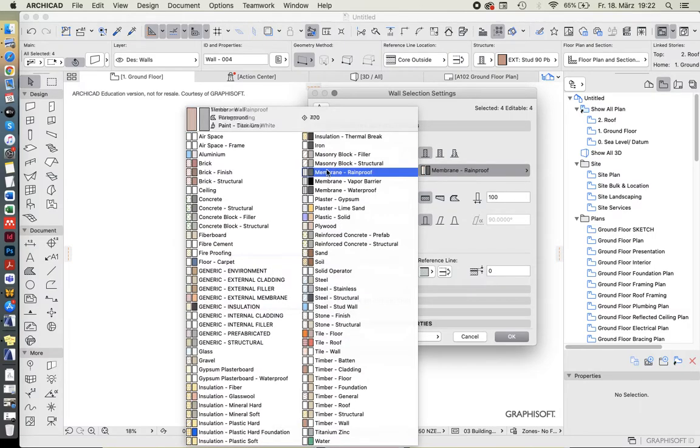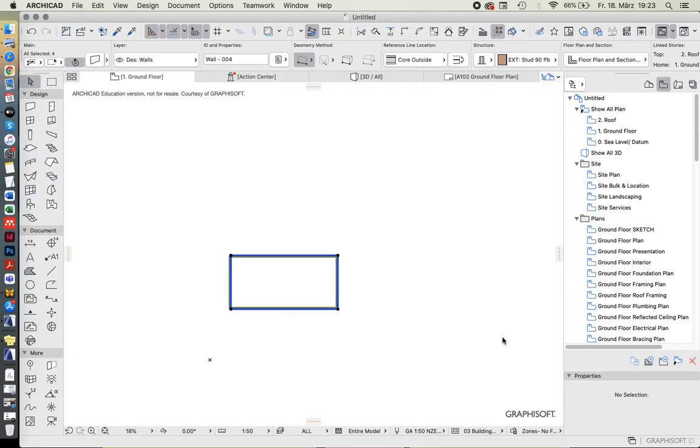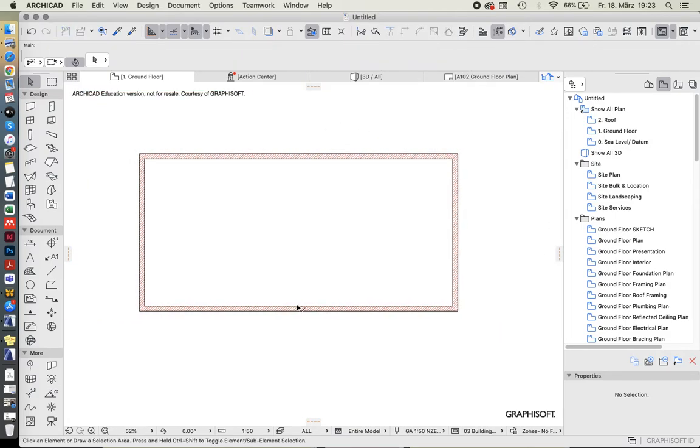It now gives you the option to change the material. We can just assume something. Let's assume we have a brick wall. We choose that one. And then here on the bottom, you can also define the width of your element. So let's assume it's twice as thick. We will have a closer look at these dimensions and everything a bit later on, just giving you a brief overview. You can press OK and you can see all these changes have been assigned to the drawing.